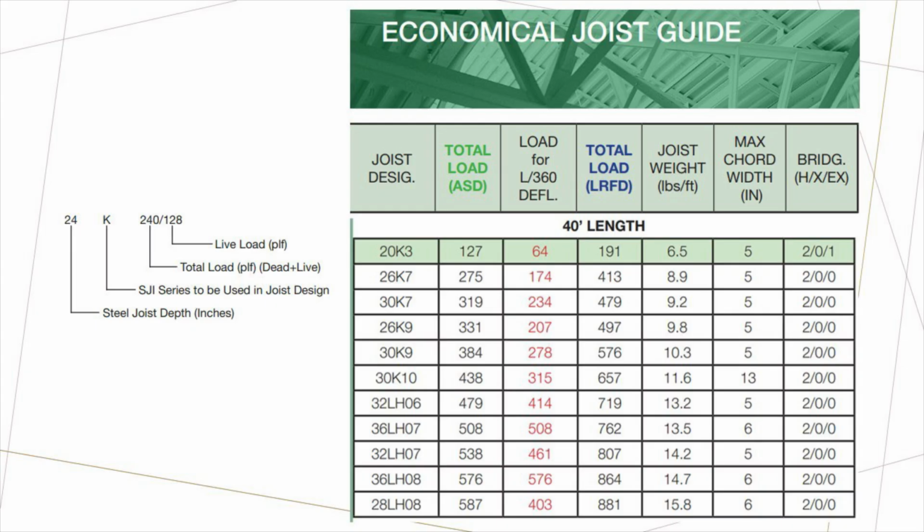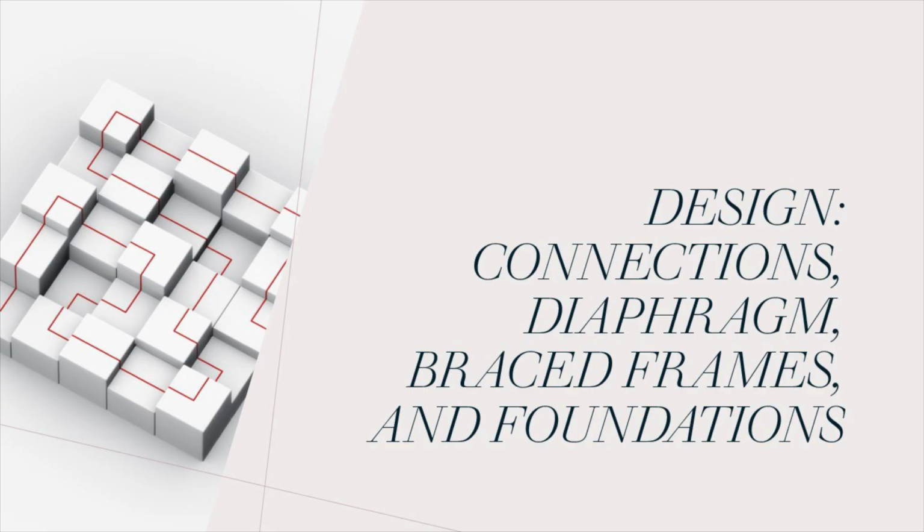Depending on how many joists frame into a beam, the worst case scenario may be controlled by multiple point loads on the beam or by an equivalent uniform load. Buckling is likely to control the design due to the columns being unbraced over their full height, so it's important to check for slenderness when determining your column sizes. The connections between framing elements ensure continuity of the load path and must be designed for the appropriate shear and moment demands. For diaphragm design, the roof is treated as a simply supported beam, where both of the reactions are technically considered the two lateral frames.